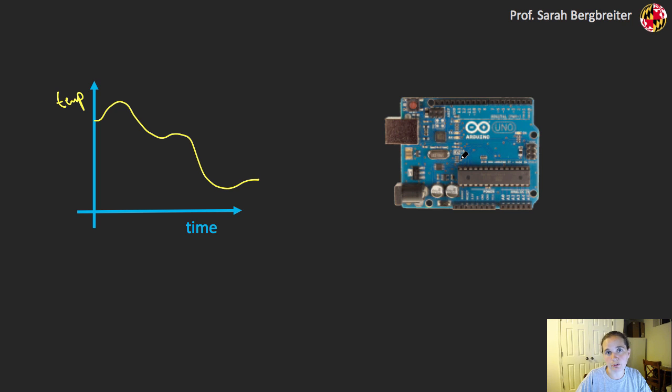Microcontrollers can often have peripherals to help you translate between the two worlds. To go in this direction, you would use something like an analog to digital converter, an ADC, or A/D is often used, analog to digital. To go in the other direction, I might use something called a DAC, a digital to analog converter, or a D to A. We already talked about the analog write functionality, so the Arduino approximates a DAC using pulse width modulation.